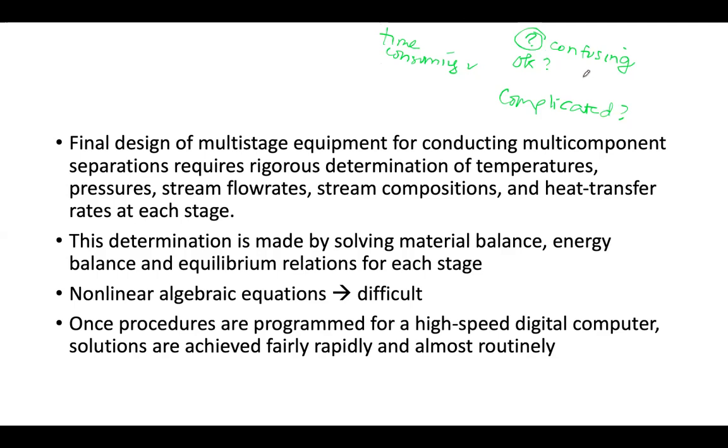Okay, so just imagine if you want to do, for example, separation of ethylene and ethane, because they have just a very little gap in the relative volatility. What I read, and I tried to do it myself in HYSYS, is that they need 99 stages. So imagine how can we do it with this Excel, right?